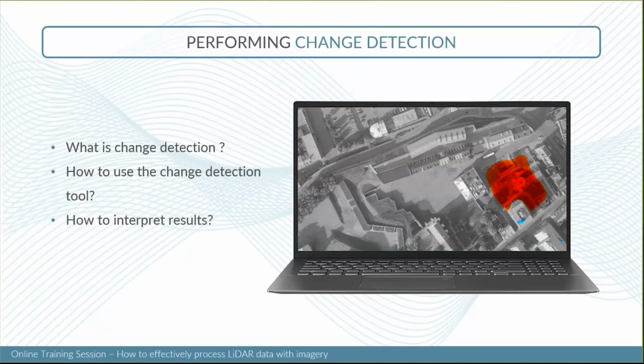So let's say I want to measure the change in height of my trees: I could use the imagery and the LiDAR the first year, and then 5 years later only fly an imagery project, and use the LiDAR DTM, which we usually assume has no big changes in terrain elevation, and then generate a canopy height model from this.